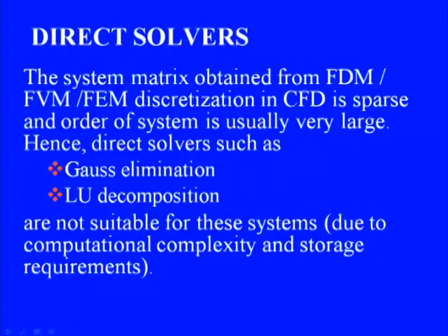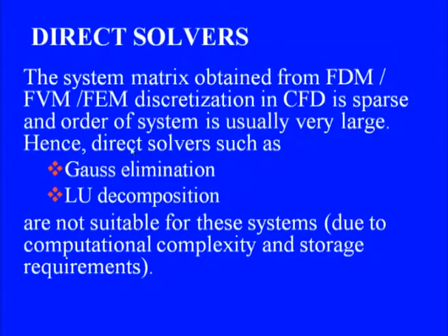In fact, they are not at all suitable for these systems due to their computational complexity, which is of order O(n cube), and storage requirement, which is of order O(n square). Even though our system matrix might take only O(n) storage, in the elimination or decomposition process we get intermediate matrices which might require a much larger amount of storage. Hence these methods are not used per se as solvers for large scale CFD applications.